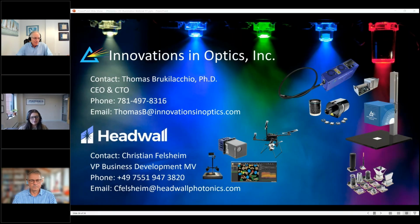Great. The last question I have here is, what is your preferred angle of the camera and the illumination relative to the normal to the conveyor belt, and why is that optimal for your application? Okay. Again, for this specific application, roughly 45 degrees, but again, it depends on what you're looking at and what the diffuse and specular reflection properties and colors of that object are.